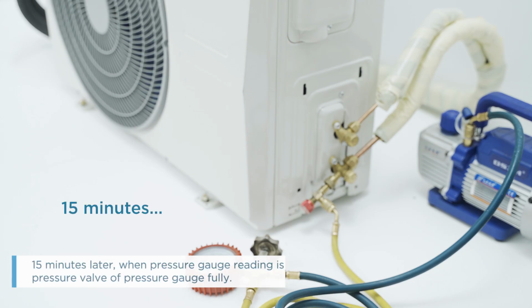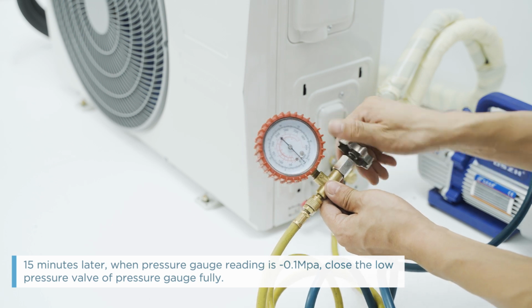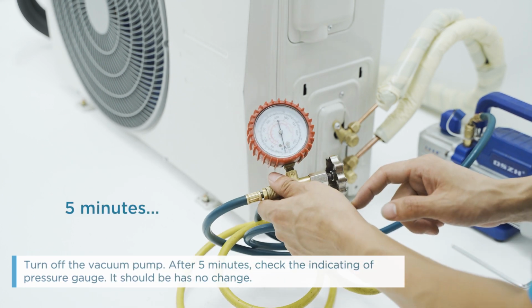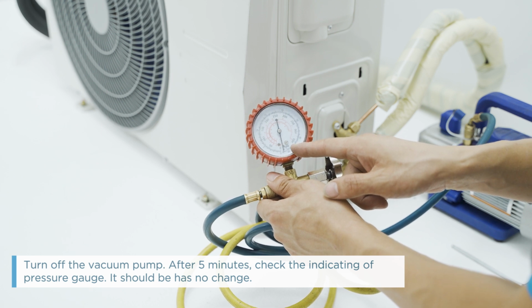15 minutes later, when the pressure gauge reading is -0.1 Pa, close the low pressure valve of the pressure gauge fully. Turn off the vacuum pump. After 5 minutes, check the indicating of the pressure gauge. It should have no change.